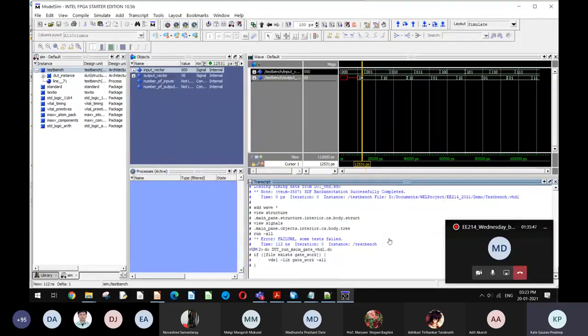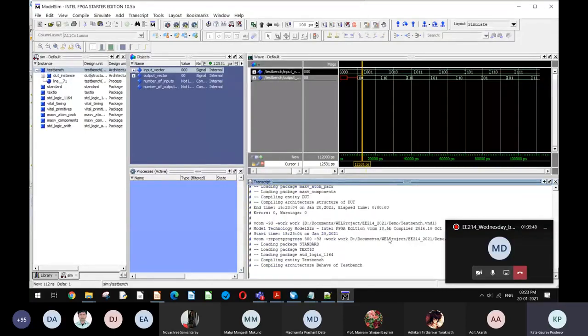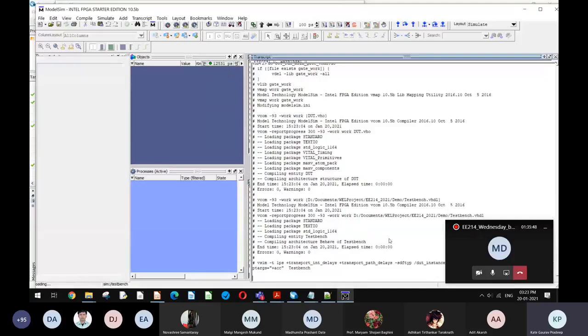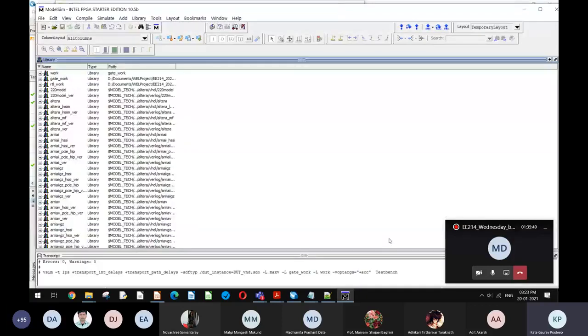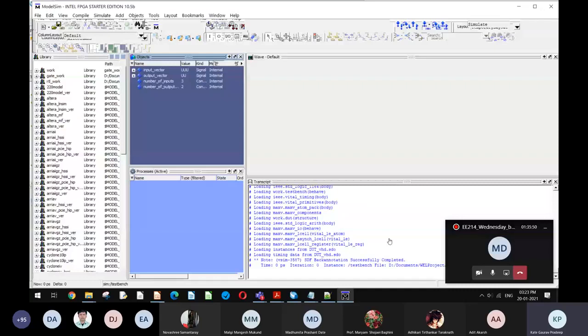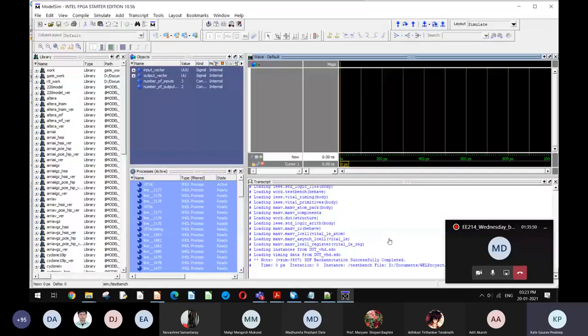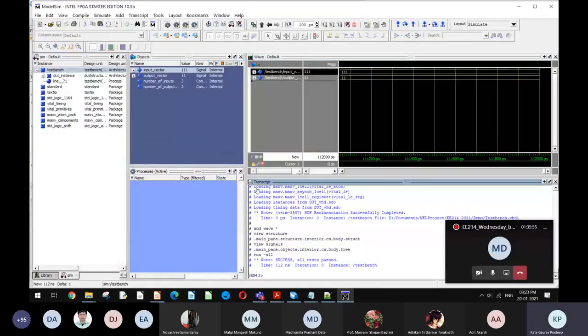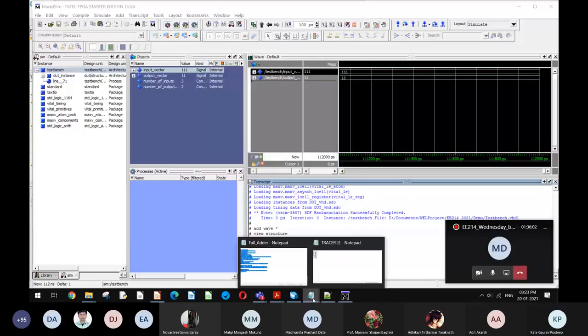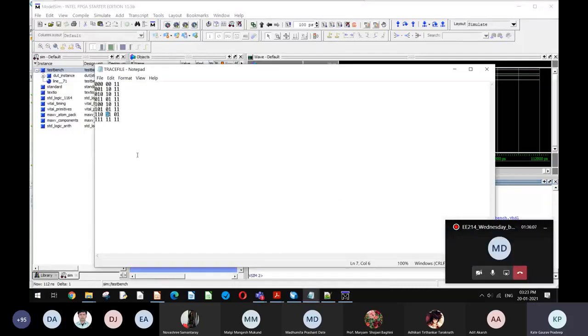Because I put 0 in that mask bit, you can see that this particular bit that I put was wrong, and this bit is correct, but the MSB of the expected output was wrong, and I just masked it by putting a 0 in this, and my test bench actually ignored that bit, and now it is showing success. So my mask bits are working.